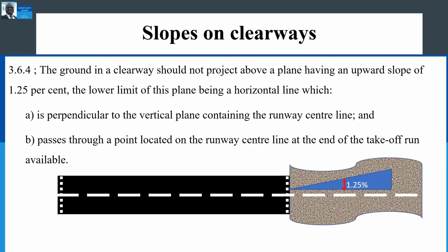What this tries to say is that in situations where the Clearway has different slopes compared to that of the runway, position yourself on the taxiway center line and look to the left and to the right. Measure half the width of the runway towards the left or towards the right, or 22.5 meters on each side of the runway center line.